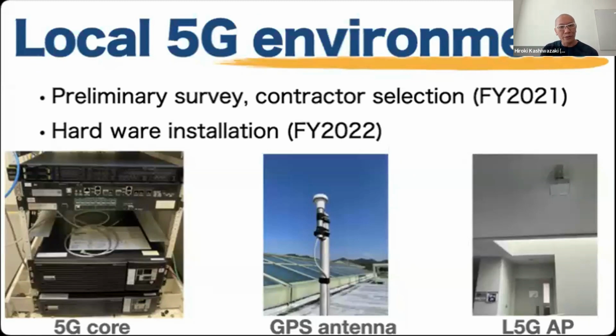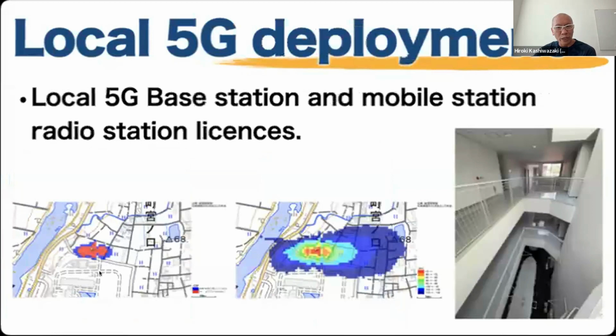As already mentioned, unlike Wi-Fi, a radio engineering license is required to use the 5G signal. In addition, the strength of the signal must be controlled to ensure that the local 5G radio coverage does not interfere with other 5G or local 5G networks. In addition to interference, the signal strength must be controlled so that it does not cover outside of the facilities owned by the individual or entity installing the base station. This is very hard work to satisfy this kind of coverage limitation.